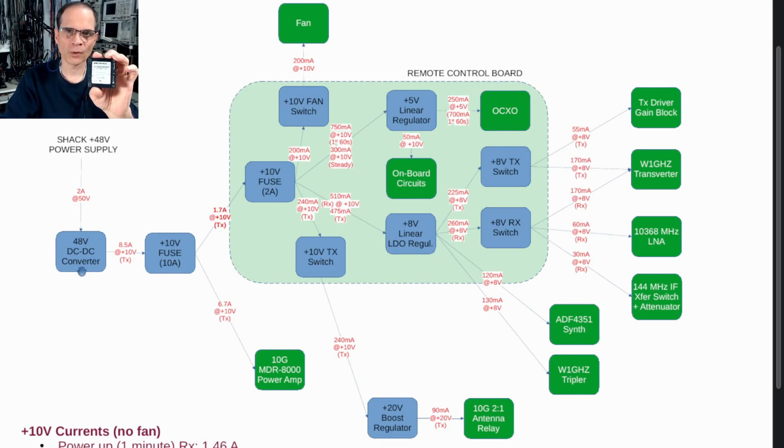So I will trim it down to plus 10, plus 10.1, plus 10.2, maybe to compensate for internal losses in the box, but around 10 volts, and it's good up to 150 watts. So no problem delivering up to 10 amps at 10 volts, as long as there is some heat sinking on that unit though. This has to be bolted down to a plate, and of course with some thermal interface to increase power dissipation. So that is what I'm going to use here.